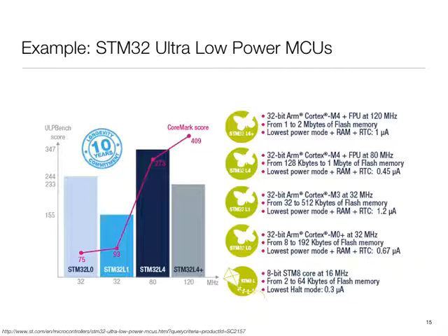So in standard computers, we take care of that speed mismatch by doing what? Caches. Now, what kind of memories are caches? SRAMs, right? They are faster, but they take more transistors, 6 transistors, a typical configuration. In MCUs, everything is an SRAM, and then you have flash memory to store the program. But you can't have a whole lot of SRAM.